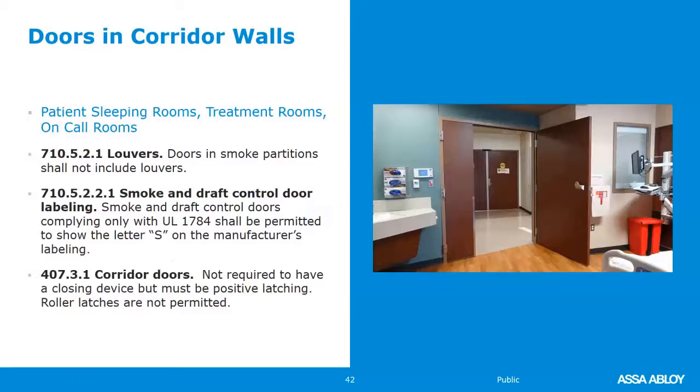Louvers are not permitted because smoke will travel faster. The louver blades will not be able to close quickly enough. If they're not heated up by fire, the fusible link will never close and the smoke will come in and harm somebody while they're still in bed.